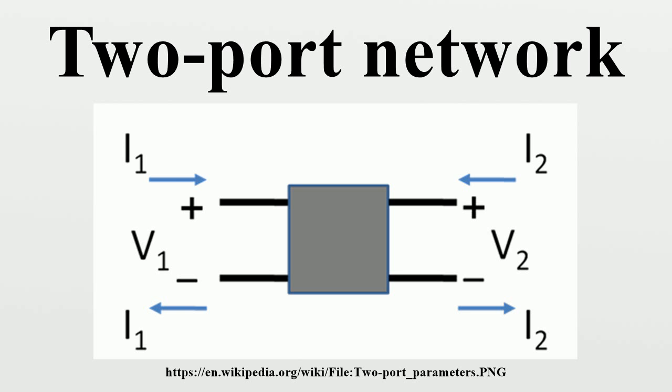Parallel connection: when two ports are connected in a parallel configuration as shown in Figure 13, the best choice of two-port parameter is the Y parameters. The Y parameters of the combined network are found by matrix addition of the two individual Y parameter matrices.